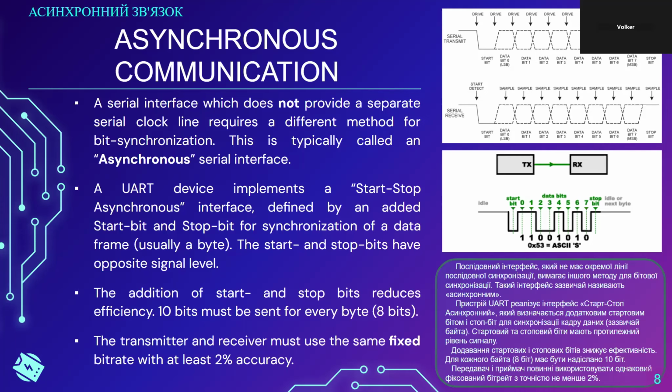Generally, if you want reliable communication to PCs or on buses like Modbus, RS-485, I would always recommend implementing a crystal oscillator on the microcontroller, even if the cost is increased. Sorry, that was a lengthy discussion for just one sentence here.